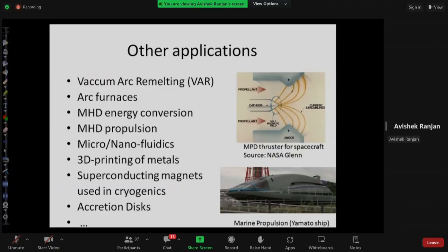As shown in the bottom, it didn't take off mainly because this is to be deployed in the sea. Seawater is certainly conducting, but the conductivity is still much less than liquid metals. Remember I said that in MHD you need to have electrically conducting liquids, and that is very important. So low conductivity liquids are not very good candidates for any MHD effects.